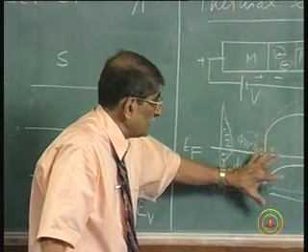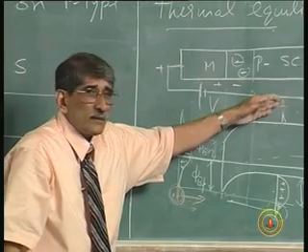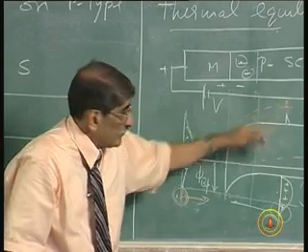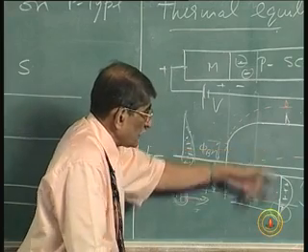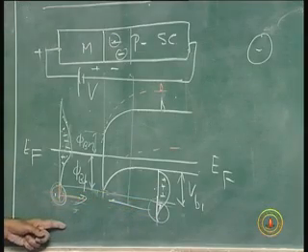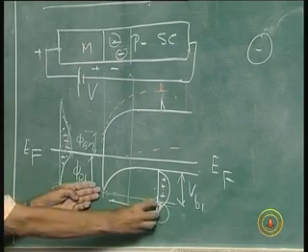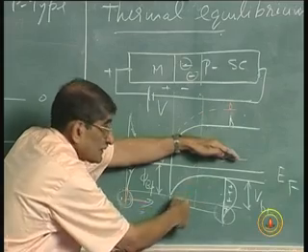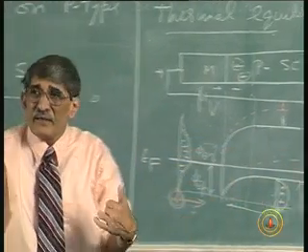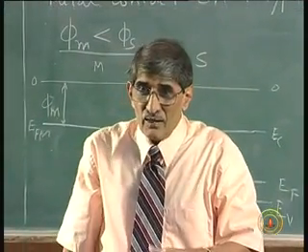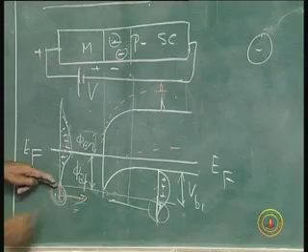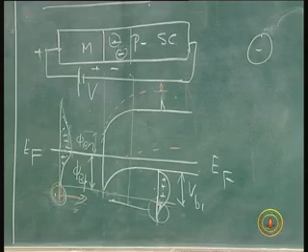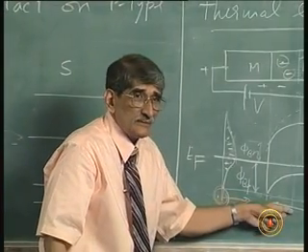So, the idea here is electron is not contributing when it goes up, because the electron concentration is small, but when this goes up, what happens to the hole concentration which we are crossing from here to here? That is going up now. So, none of these holes have enough energy. This is a barrier for holes, they have less barrier, more barrier, they are not able to cross. But this number crossing from here to here remains the same. So, you will have now current due to these holes which are crossing from here to here.